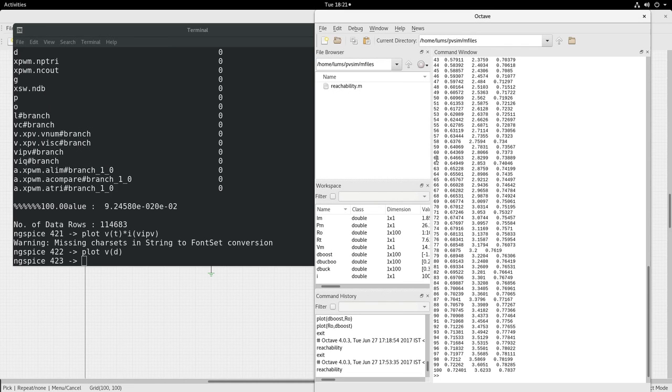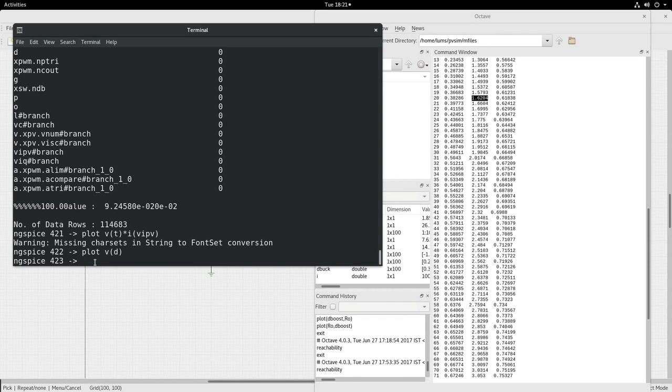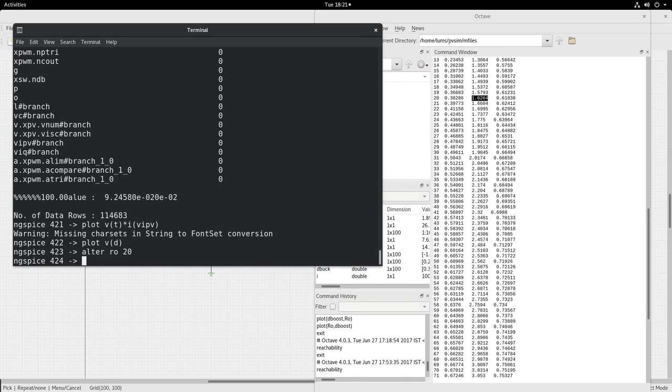What happens if I set R0 to 20 ohms? At 20 ohms, the duty cycle required is 1.62 for the buck converter, which is an invalid value. The duty cycle should be between 0 and 1, and therefore if R0 is 20 ohms, you will never be able to achieve peak power. However, at the same duty cycle, if you put R0 as 20, the power drawn will be very less. For example, alter R0 to 20, and the duty cycle control voltage VC is still 0.62.